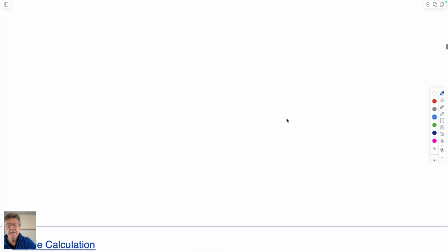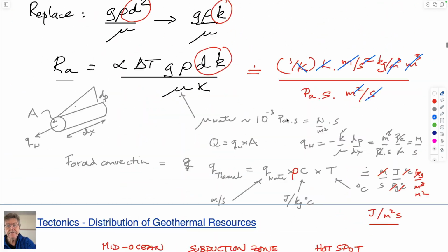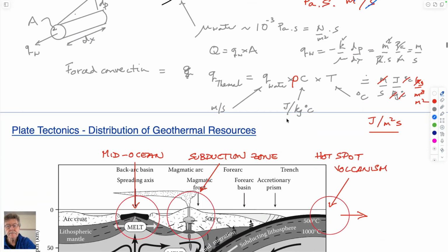In the same way that we calculated advective fluxes, this advective flux was the density and heat capacity multiplied by the temperature that's held in there. So this would be the temperature that's held upstream. This packet of heat is carried downstream at this velocity, and so the rate at which this comes out physically as water is this velocity multiplied by its cross-sectional area.